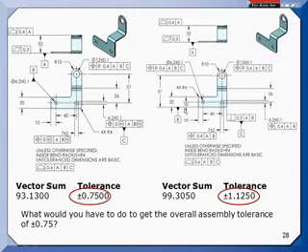So if the supplier says I'd like to use this as my datum features, B and C as shown over here, I'm going to say fine, but I'm going to have to greatly tighten this position tolerance and that tolerance to get the same result in my assembly. And usually when I say that, they'll back off. They'll say, no, I want those bigger tolerances. And so they'll go along with this functional approach.